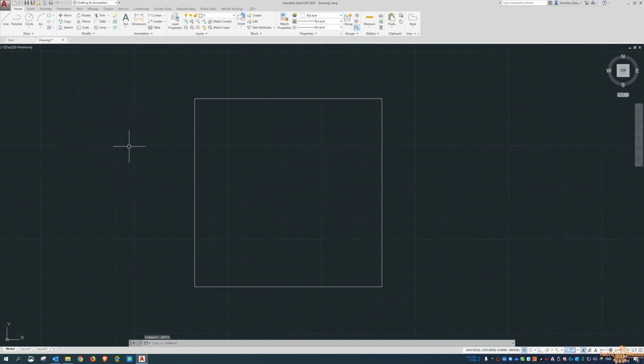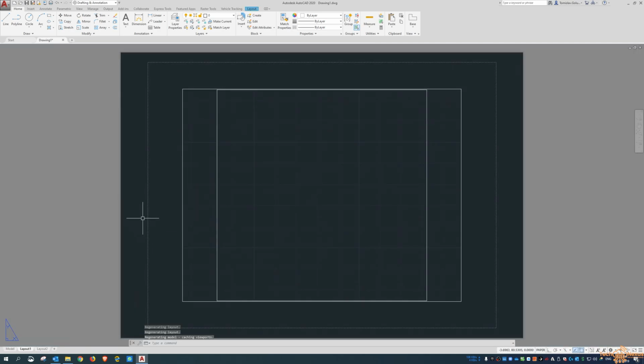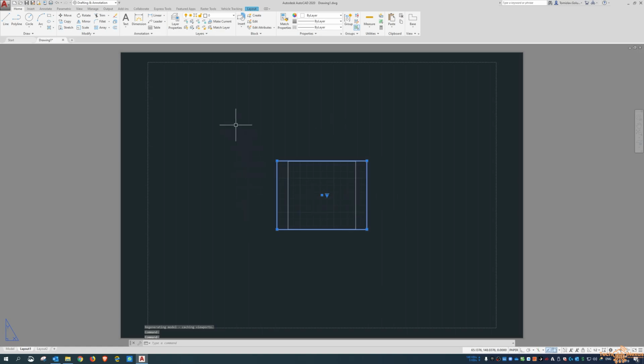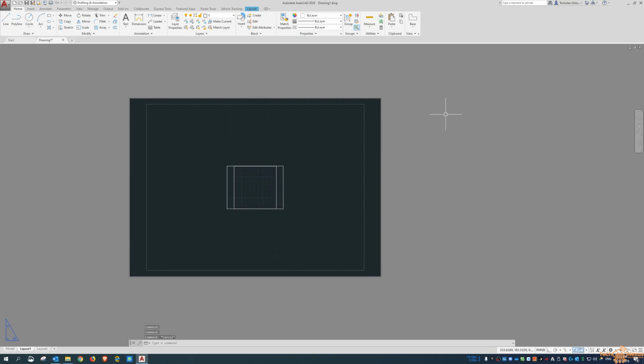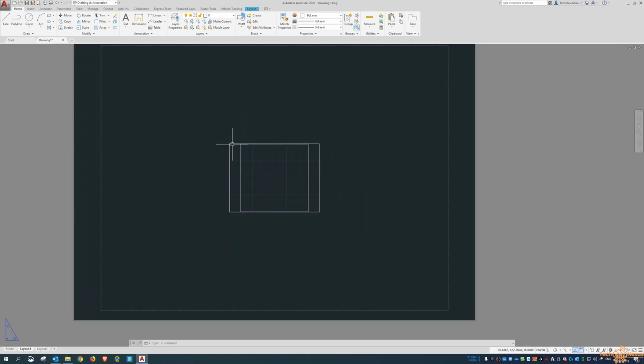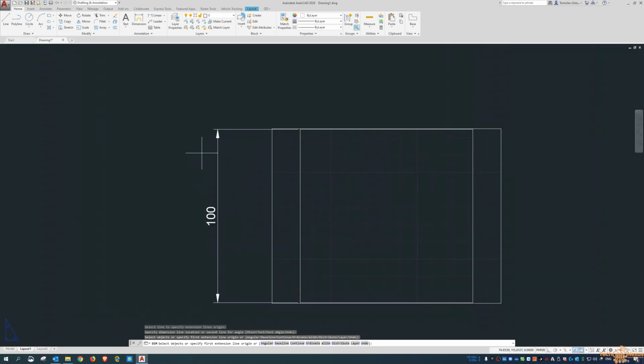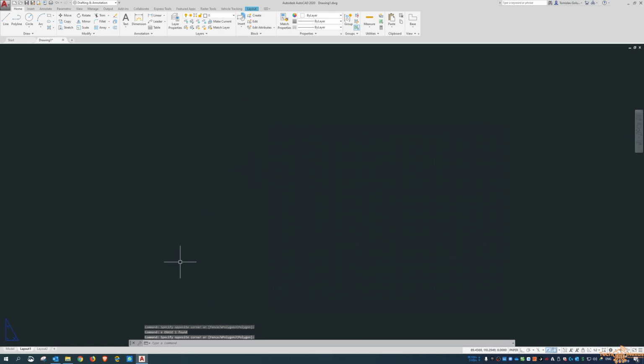So this is the GUI, and the layout is for when you're putting a scale on the viewport on a sheet. I might cover that later in the week, but essentially the paper space tabs, or the layout tabs down here, is the paper space. It is literally the paper that you put onto your board or your desk, and these viewports are scaled to suit, so everything you have here at 1 to 2. Even if I dimension that item, you can see it still comes out as 100 millimeters, even though we've got a 1 to 2 scale on it. So you have all of those options.